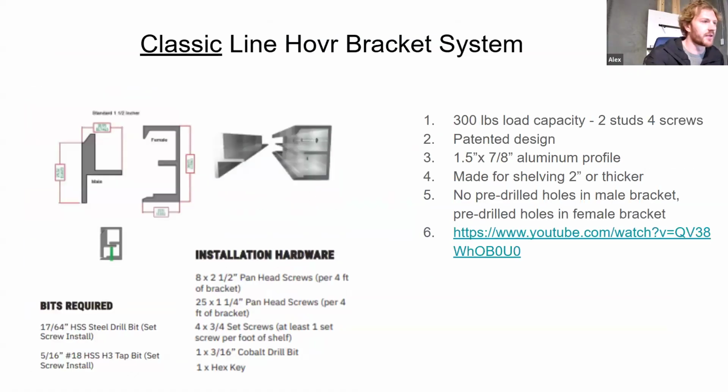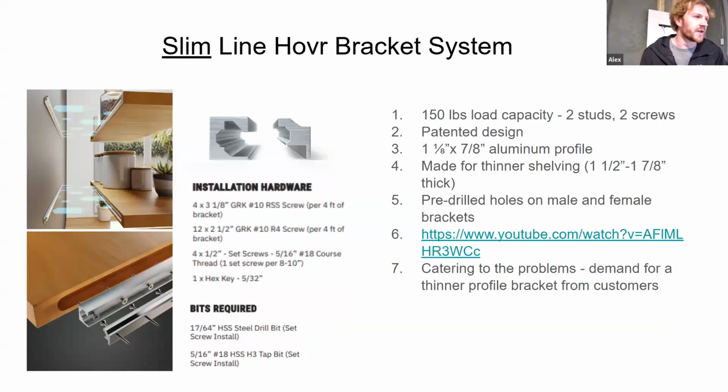Sorry, going back to the classic here. Again, that's 300 pounds in 2 wood studs at 8 inches off the wall when weight is distributed evenly, and that's how we calculate the load capacities on all our bracket systems.